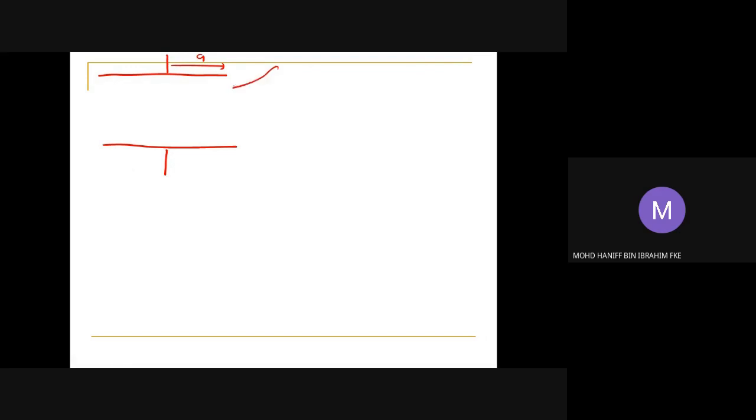We have this as the a, the radius. So in between, we have the dielectric of permittivity epsilon, sigma as the conductivity, and also mu naught as the permeability. What I'm going to do here is use Ampere's circuital law, the ACL, to find the H field inside this dielectric.